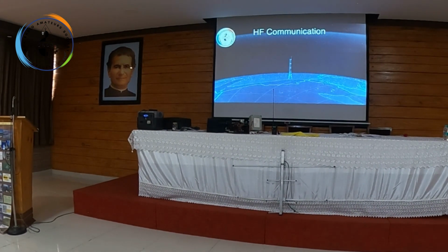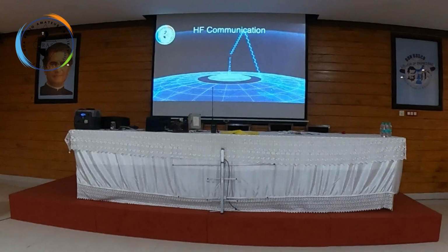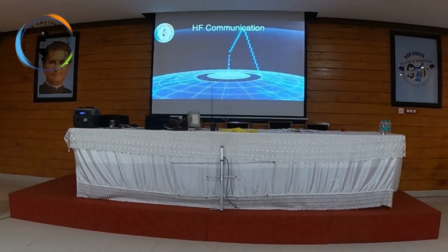To reduce or overcome a skip zone, the takeoff angle of the antenna is adjusted. By using a higher takeoff angle for the HF signal, the ionosphere is used to refract the signal back to Earth at a shorter distance. All sorts of voice, data, or signals can be sent using these waves.